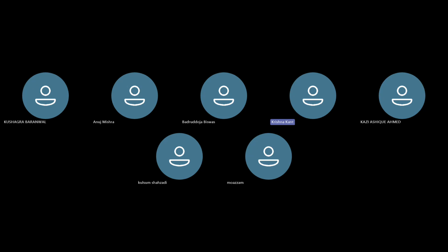So what is happening here is, whenever we are working in the landscape, before that we have to load the link of the building, and after loading, we don't exactly hide the element, but in the visibility settings we turn it gray, so we lower its visibility, okay.